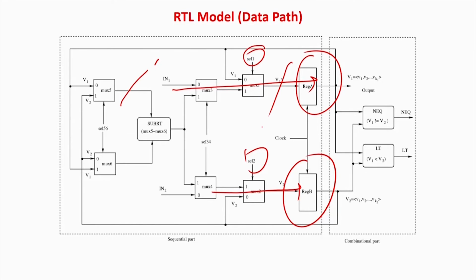That means either the number is 1 or the number is 0. But say, for example, I am taking a 3-bit number, let me say 001. In a stuck-at fault model at the gate level, you will see whether this line is stuck at 0 or 1, this line is stuck at 0 or 1, and this line is stuck at 0. But at the RTL level, this whole number is considered as a single number.